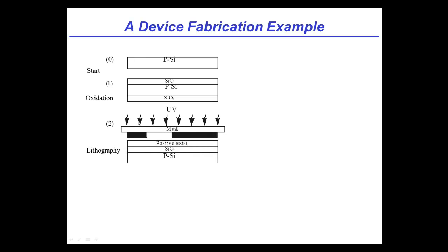So now we're going to do a lithography step. Spin photoresist, and we're going to place our mask with our chrome regions that are going to block light. We're going to shine UV onto that photoresist, and after we expose it, we're going to follow all of the lithographic steps of that previous slide. So we're going to be left with photoresist here and here. Okay, and get rid of the mask.